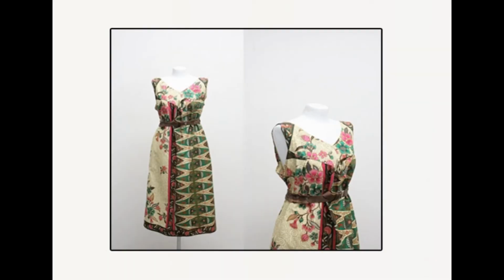And so the knitted fabrics, we have to be very careful, and at the same time, if you stretch the material and if it contains little wool and other materials which are not that stretch resistant, there will be a problem. The resin finished cottons, for example, cannot be straightened, because they will be given treatment, and they are also treated at a very high temperature; you cannot straighten them. So, if you find that that particular fabric is not having right angle to each other, the warp yarns and weft yarns, then avoid that material.